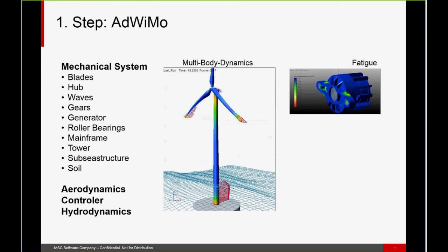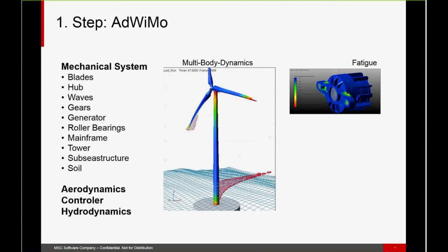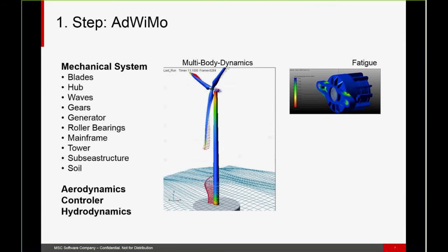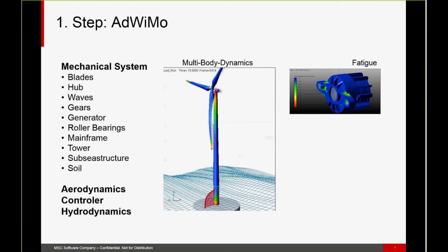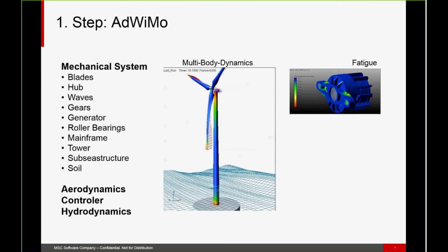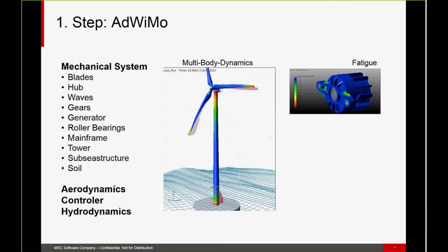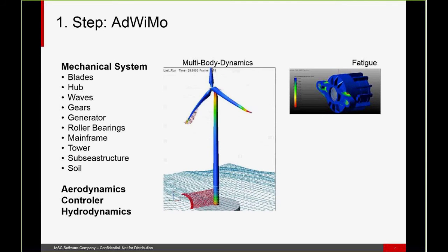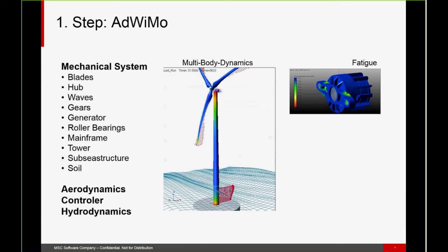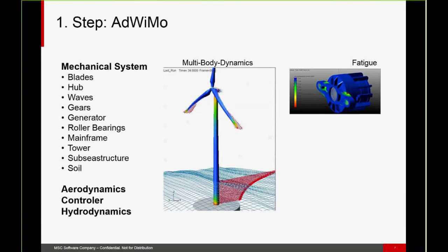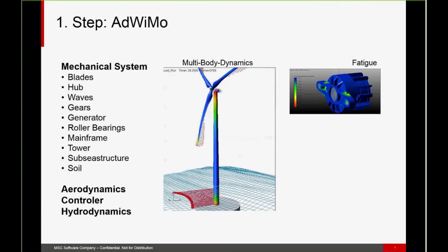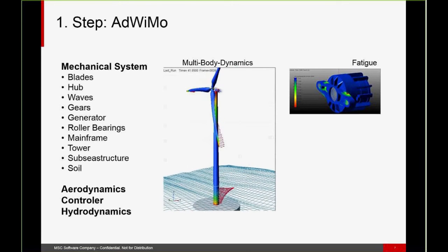The point is that the user should get an insight about the fatigue behavior right at the beginning of his design, because ADAMS normally is used at the beginning of the design process, and therefore you can check or evaluate a big variety of different concepts, and all the time you can perform immediately a fatigue simulation to get also an evaluation of the fatigue behavior, which is normally in the typical process chain a step which is quite a bit later than the original concept design phase.